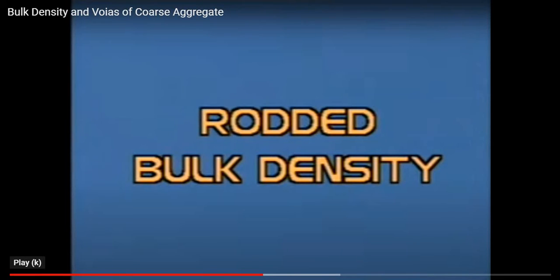So guys, here we are taking two types of bulk density. Number one was the loose bulk density, that is the density of aggregates when the aggregates are loose, meaning without compaction. Now we are going to calculate the bulk density when the aggregates are compacted. That's why it's also called rodded bulk density, because we are going to compact the aggregates with the rod. In this one we are going to put the aggregates in 3 layers, and after each layer we are going to compact it 25 times. We will see it here now.